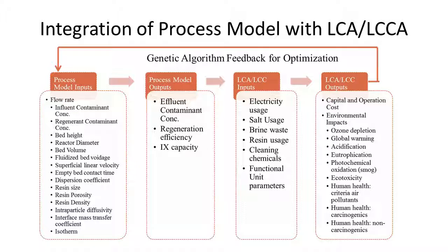And then this has come up before when I've presented at different meetings of this group: what does it mean for an existing plant? It's one thing at the design stage. For an existing plant, some things are fixed, possibly like your reactor configuration. But you could look at things like the resin or the regeneration chemical, and depending on how the system is designed, you often can't change the reactor, but you can make some tweaks to how the regeneration is done. So I think an existing plant could make some reasonable changes to the regeneration, and that could be reflected in this tool.